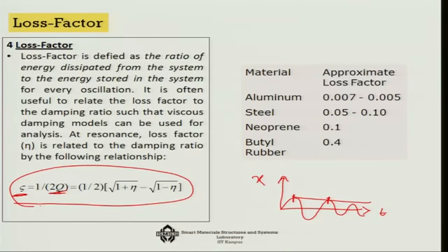property, because the more hysteresis there is in the material, for example, the more this kind of energy dissipation there will be. For some materials, for example aluminum, you will see that the loss factor is much smaller in comparison to steel, which means steel dissipates more energy inside it. And rubbers, which are generally used as damping materials, have a much higher loss factor, an order of magnitude higher. That is why we use rubber or neoprenes etc. as damping material, unlike the metals. Generally polymers have much larger energy dissipation, and hence eta is much more for the polymers.